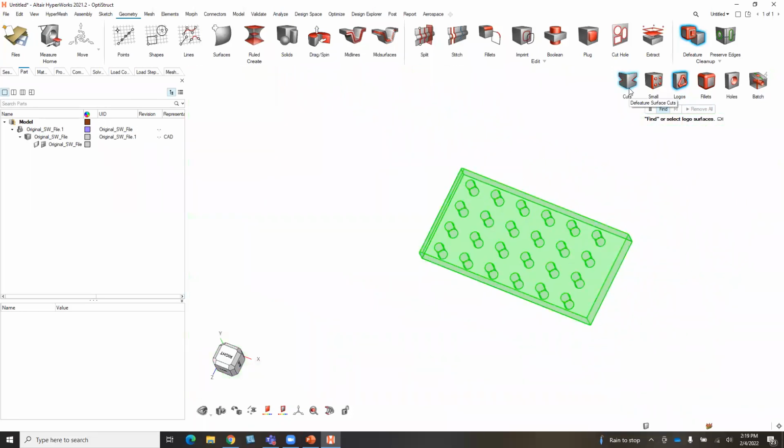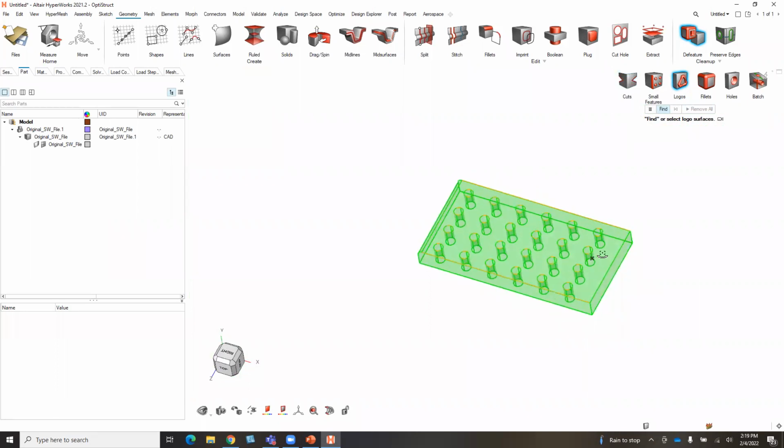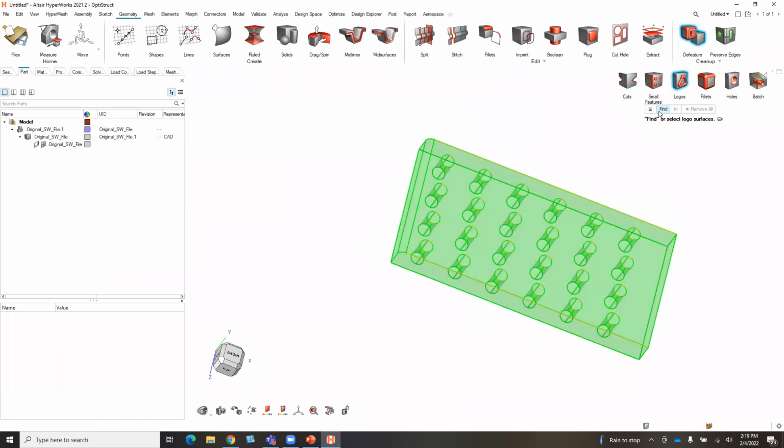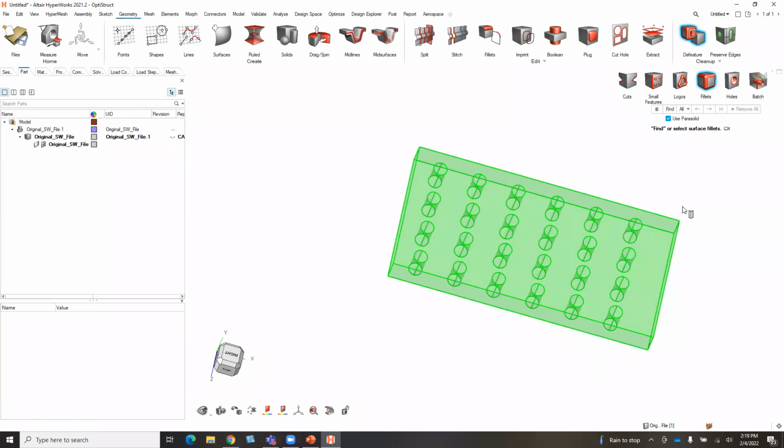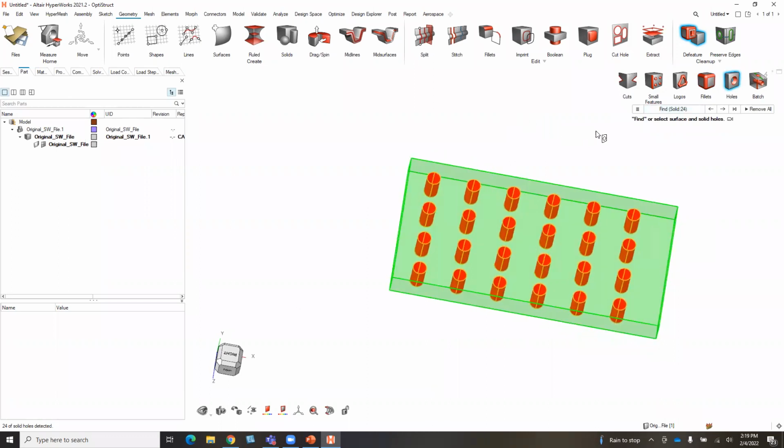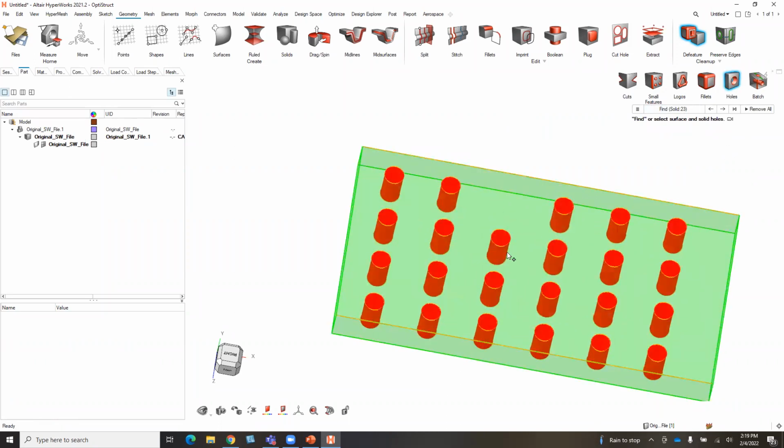Another common thing I might see in sheet metal applications is cuts coming into the tool, and actually changing and removing cuts. But in this case, I want to remove this fillet now. So I'm going to go to a fillet, just click on it and hit remove all. All right, great. So you see it. Rather than having to go back to the actual CAD tool, I can make these changes on the geometry accordingly. Last thing, let's look at the holes. Hit find. Now in this case, I don't want to remove all the holes. One of the cool things is I can zone in. Rather than doing everything at once, I can do individual components. So I can just click on highlight in this face, see how I'm removing the hole.